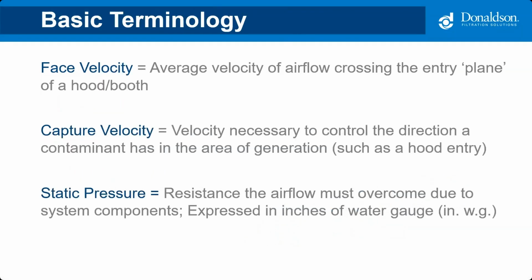And I guess the biggest other little bullet point on this is that the difference between dust collection ducting and standard HVAC ducting is that when you're handling dust collection dust, you're pneumatically conveying a material as opposed to moving air. So that's why this Q equals VA becomes so important.